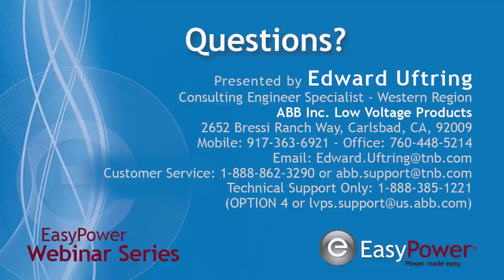So the I part of the I squared T is something that we can't control, right? The short circuit is going to come in with whatever amount of current it's going to have. What we can do is mitigate the time that it takes. Again, going down to 2 milliseconds, we're saving you almost half the amount of let-through energy. So you're not going to see a huge amount of power coming down the line since we cut it in half. Most people use 4 milliseconds, which doubles. Again, you're looking at 2 milliseconds for T rather than 4 milliseconds for T. So we halve the amount of let-through energy, so half the amount of energy that anybody can see down the line from that MCCB.